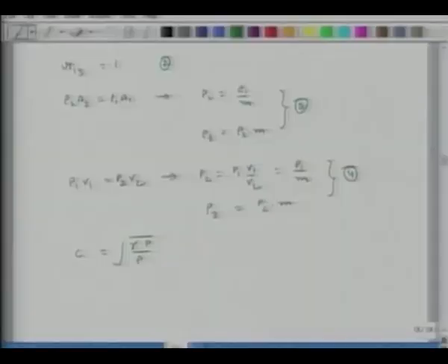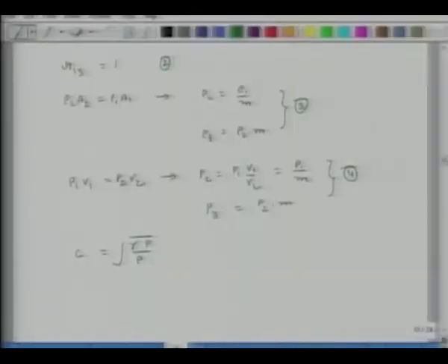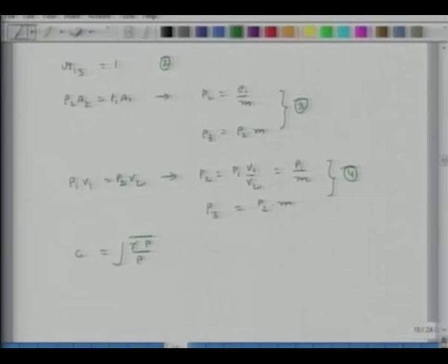So in these P1, P2 and P3, they are basically average pressures, bulk pressures in each of these chambers, first chamber, second. Around these mean values of pressure, there are fluctuations in the pressure because of sound. But even if sound is not traveling through this whole expansion chamber, still P1, P2, P3 will hold.